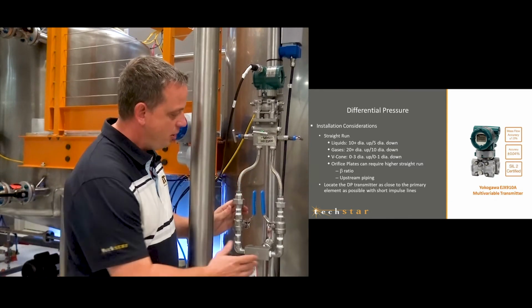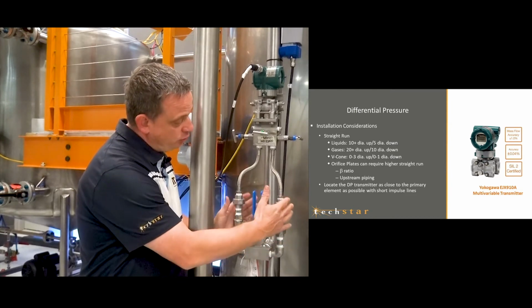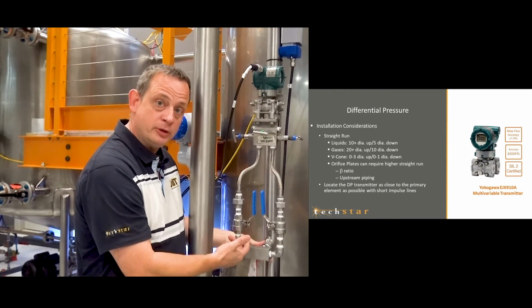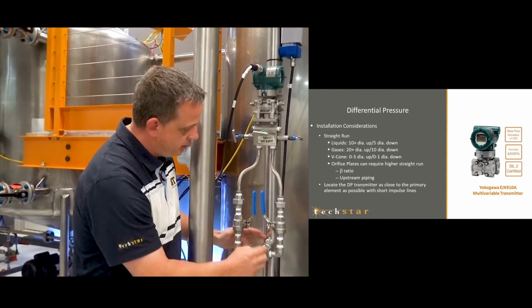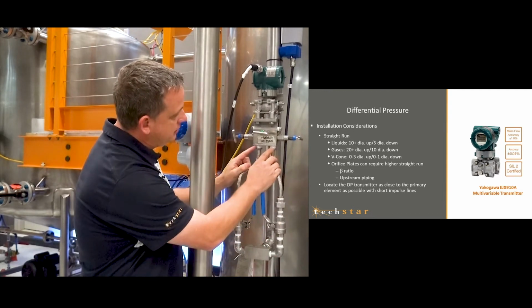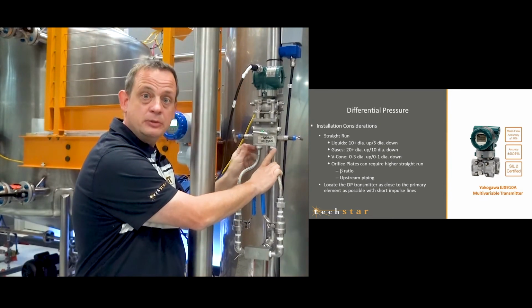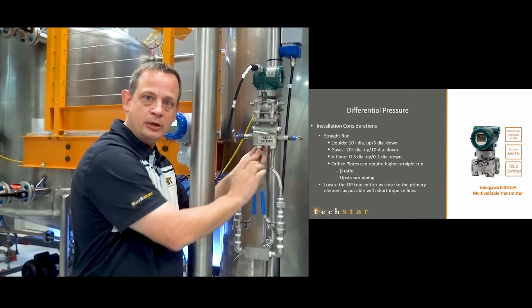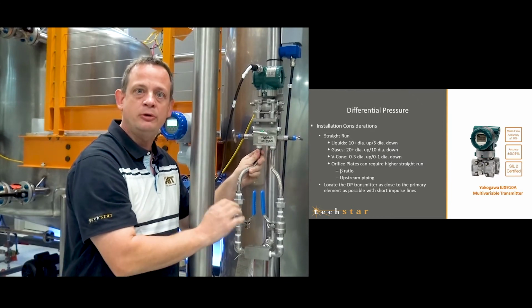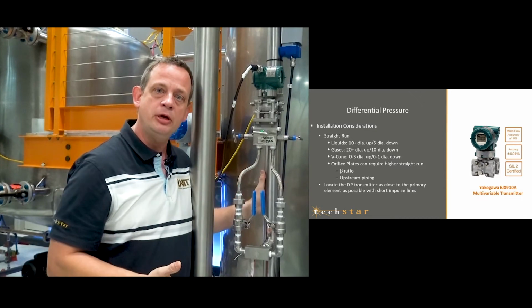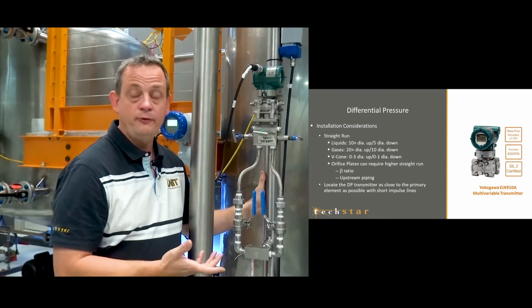So really what you want on these is you want them installed where the transmitter is below the flow tube when you're in this vertical installation. The reason for that is otherwise it makes it possible for air bubbles to get entrained in here, which means I have to bleed the air out every time maybe my system goes down or the pipes go dry. I'll have to sit here and bleed it out. We did this on purpose here in our training center, mainly for training purposes.